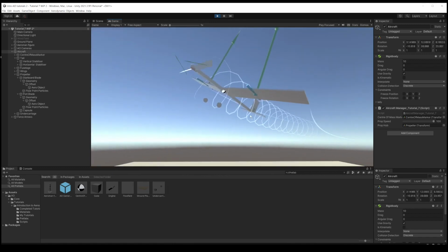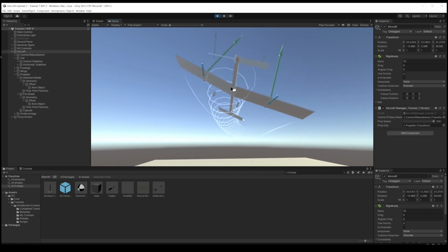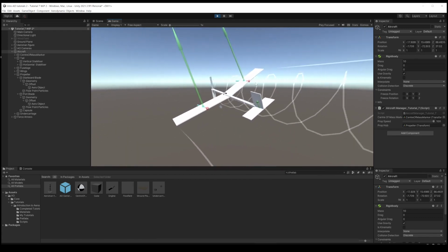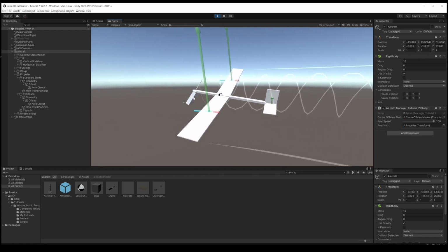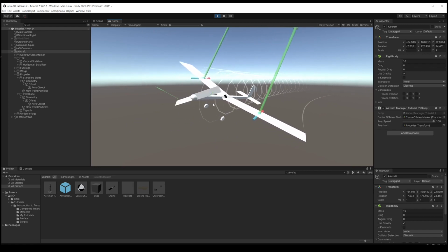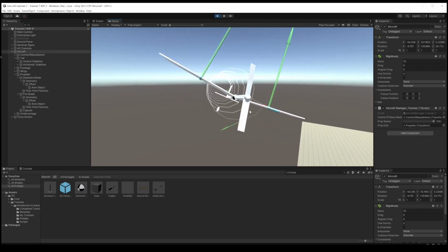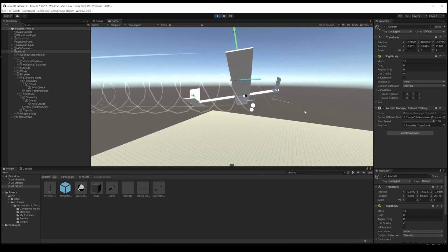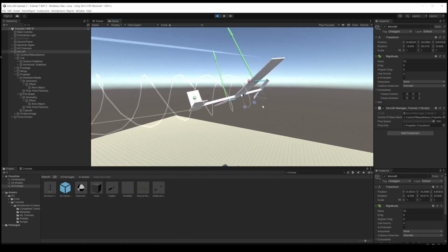You may notice the plane is flying in circles, even though we've got the fin straight, and that's a true aerodynamic effect. Happens on real aircraft. There's drag torque on the propeller when it's spinning around, so there's drag on those wings going round. And what we're seeing here is that the drag torque is actually tipping the plane over, and if we spun the propeller the other way, it would turn the other way.